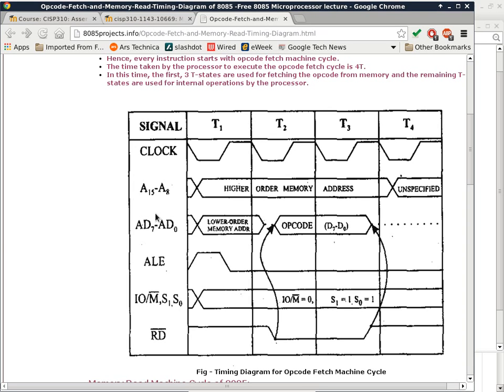And I'm not kidding. Some people use a Sharpie and draw out the circuit on the circuit board, and then they dunk it into corrosive solutions. And the Sharpie is resistant to the corrosive solution used to etch circuit boards. And when you're all done, you pull the circuit board back out, you clean it really good, and then you use an organic solvent to remove the Sharpie paint, and then you have your own circuit board. Wow. Yeah. And then if you are dealing with bigger components, through-hole components, you can even use a drill press and just drill your own holes, and then you can attach your own components onto your circuit board.